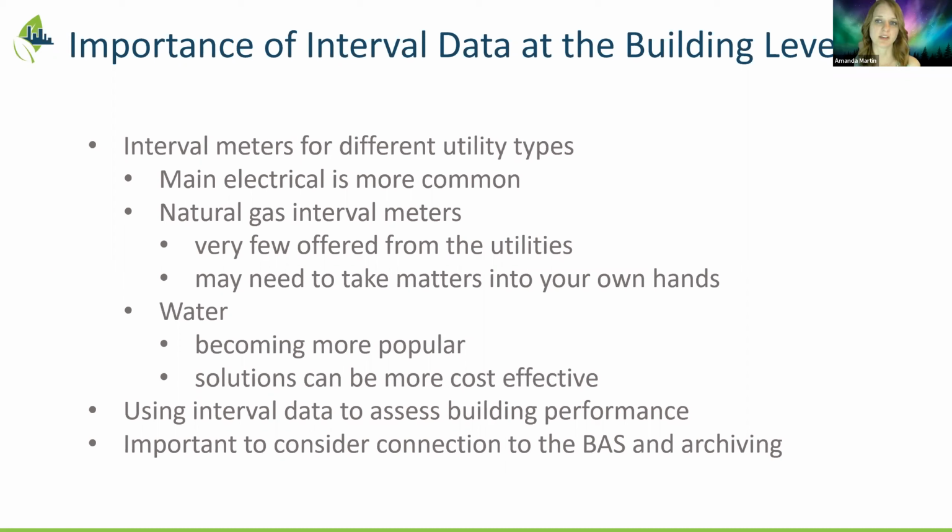During the pandemic, when we were trying to partially or fully close facilities, we were tracking loads and performance using those meters as well. On large projects, usually if the savings is over $10,000, we would put in a meter so we could use it for measurement and verification purposes. Ideally we get it in before the project takes place by at least a year, so we can track the baseline pre and post after the retrofit is completed.